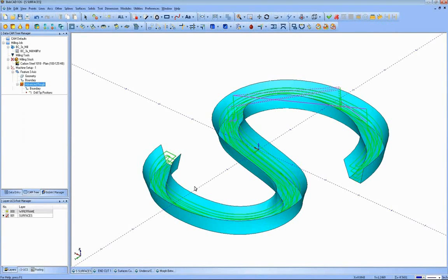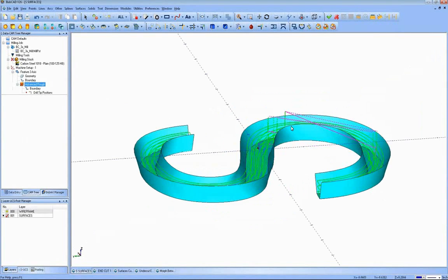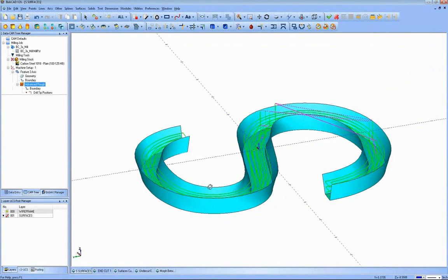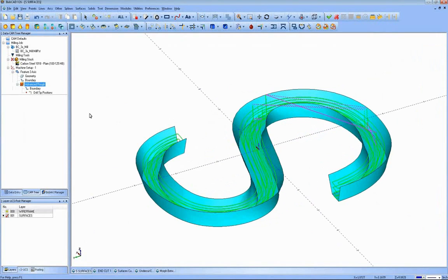It's going to leave different types of cutting and different loads, where you might want just that continuous back and forth cutting motion. It also wants to start in the middle versus on the end, and do connections at that point. So let's take a look at how to apply a multi-axis toolpath to this to output in a 3-axis format to get the type of cut we're looking to do.